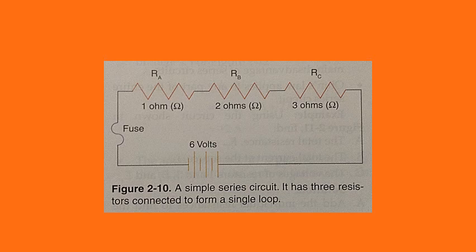The total voltage at the source is equal to the sum of the voltages of the resistances, or the voltage drops at each resistor. The voltage at each load is calculated using Ohm's law, where voltage over resistor A equals the amperage A times the resistance A, as seen on your screen.